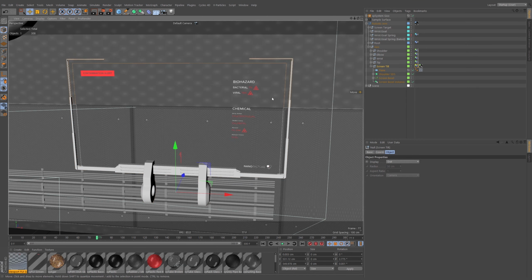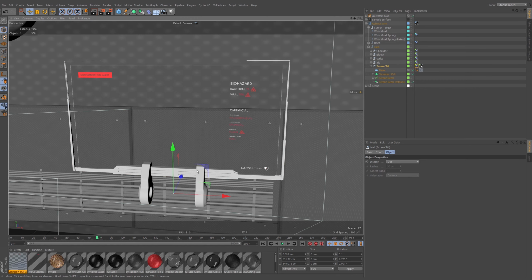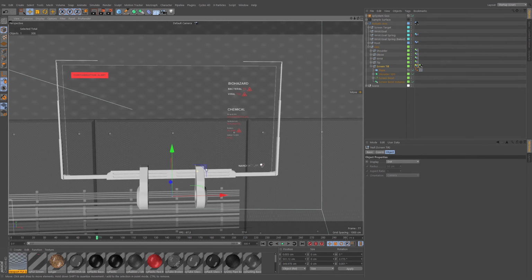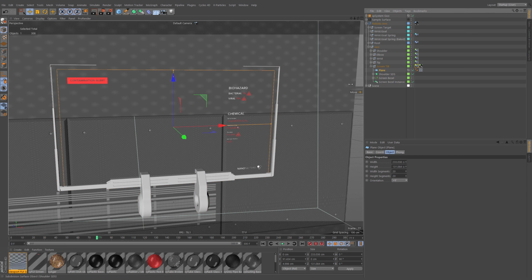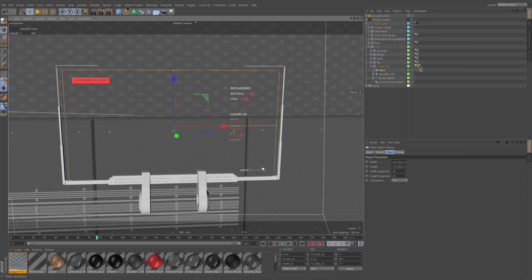We're going to align a work plane basically to this geometry. If you've never done that before, don't worry. We'll cover it in a second. In fact, if I go into my plane here, and I go into this option over here, you can see there are these two axis grids, or work plane grids, sorry. And you can align them to different axes. I'm going to align it to the selection. So I'm going to align work plane to selection.